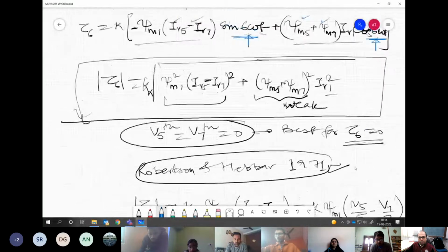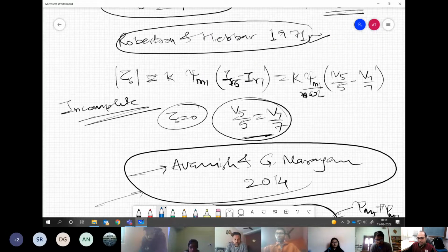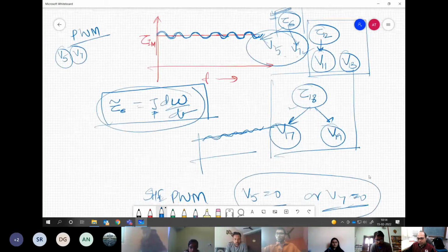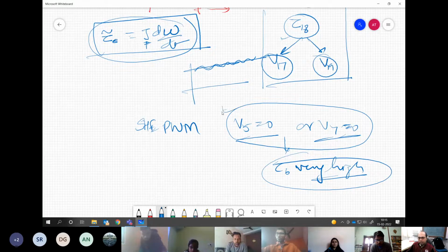Now that kind of thing is gone. So this balancing act which was there earlier, now one factor is gone, so the other may increase the sixth harmonic torque tremendously. That is one more disadvantage when we simply try to eliminate one harmonic. Sometimes we may encounter a very high amount of harmonic torque in the system. You are eliminating one, but you have not seen what the other is doing. The other one may be very high, and so the total effect on the sixth harmonic torque may be very high.